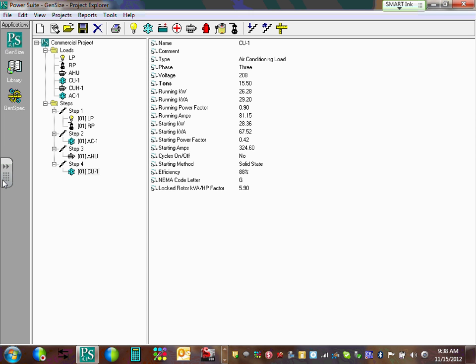You got it. But why do you think I do it in mechanical equipment, not in the lighting? Because mechanical equipment have controllers. They already have controllers. I can interface a timer and make it control the equipment, just delay the start. We're talking about, guys, maximum, everything will be up and running within 2-3 minutes. The delay is not hours. The delay is just seconds.